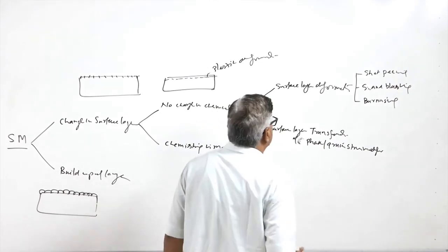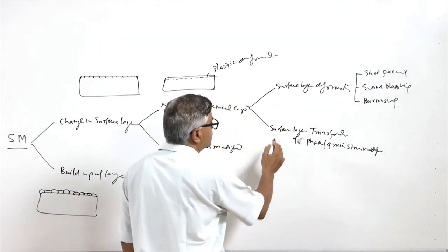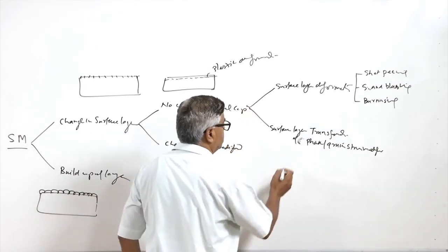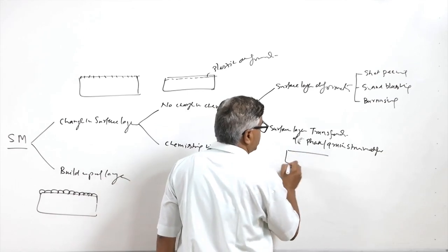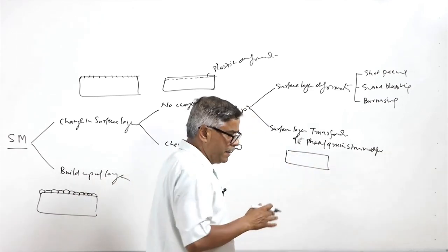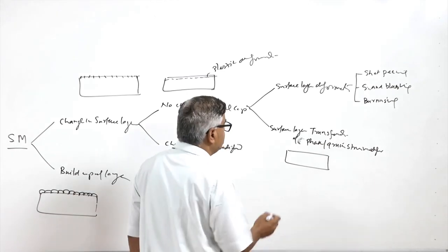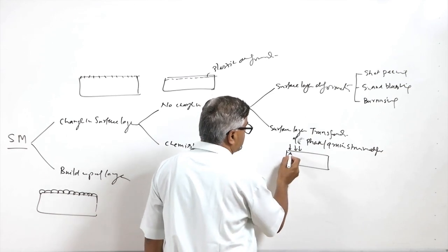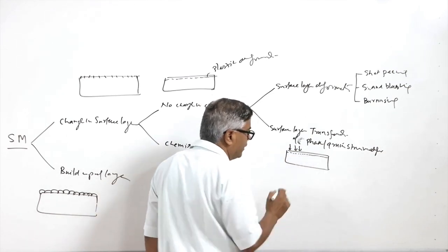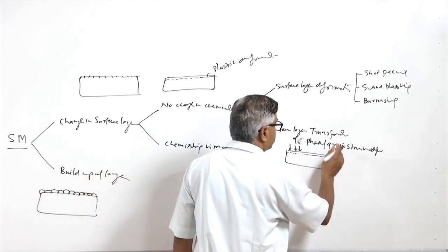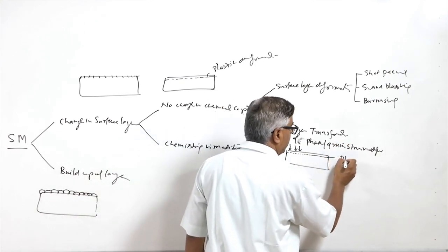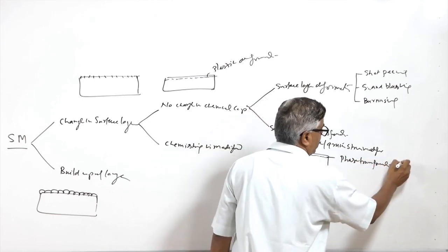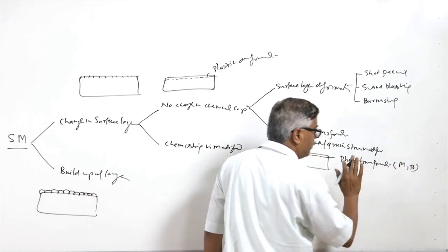Or shot blasting. Then under the second category, surface layer transformation is achieved without any change in chemical composition. In this approach, basically using thermal methods, the heat is applied just near the surface layers. So either a structure gets transformed into some harder phases or a structure gets refined. There are two approaches, one where phase transformation is realized, like martensite or bainite is formed intentionally,